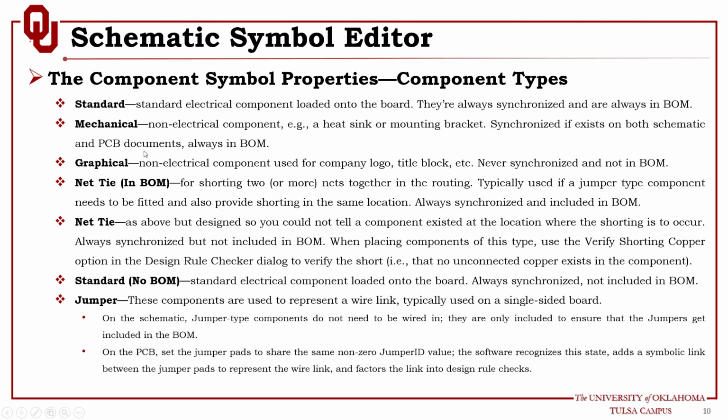Now, mechanical components are non-electrical components. Of course, it says mechanical, that means it's not an electrical component. But why do you need it? For instance, if you want to add a heat sink, or add mounting brackets, or add fiducials for PCB assembly, or add any other mechanical identification symbols, you can use a mechanical type.